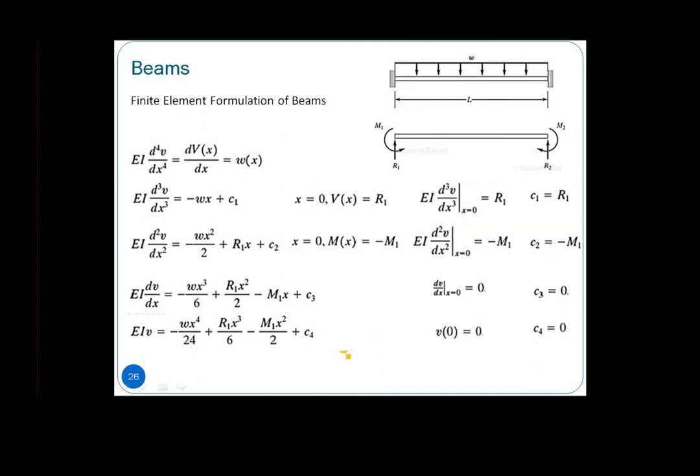We have this summation of FU. If you find its minimum of work done, we minimize del summation of FU over del U_K. That will give us our F itself. So using this, we can find our load matrix. Another method is computing the reaction forces, then taking the opposite of these reaction forces, which will be the equivalent loads applied to the nodal points.